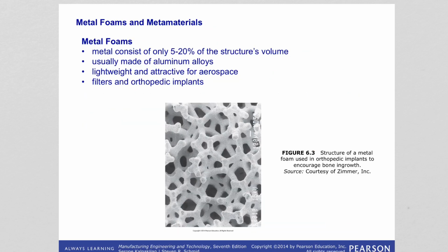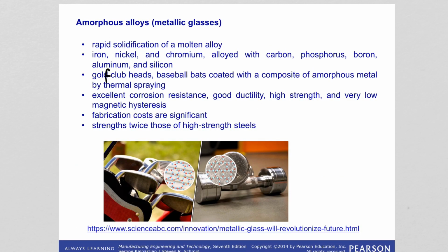So let me see if we have a figure. Okay. What it means is, when we apply an external magnetic field, ferromagnetic materials such as iron, the atomic dipoles align themselves along the magnetic field direction, and when the field is removed, sometimes that alignment still remains. So we say the material has become magnetized, and even if we remove the field, it will still stay inside the material indefinitely.